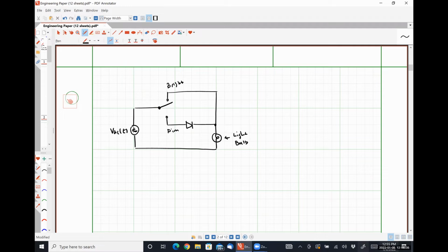The other quantity that we need to be interested in is the peak inverse voltage, or the PIV, okay? So the peak inverse voltage is effectively the largest amount of reverse bias voltage that is applied, because we also want to make sure that we never get beyond our breakdown voltage, which is going to mess up our rectification as well, right? Because we know that beyond the breakdown voltage, our diodes are capable of carrying large amounts of current. And so we won't cut off those unwanted portions of our signal.